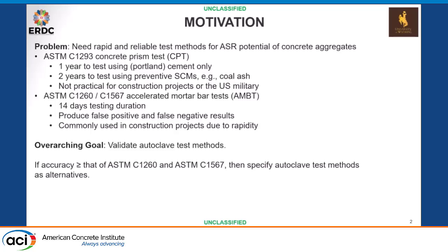1260 and 1567: one is the test for aggregate reactivity, and 1567 is if you want to use SCMs. It's a 14-day test, and we know that it's plagued with false positive and false negative results. We do use these. We specify this for all of our projects.